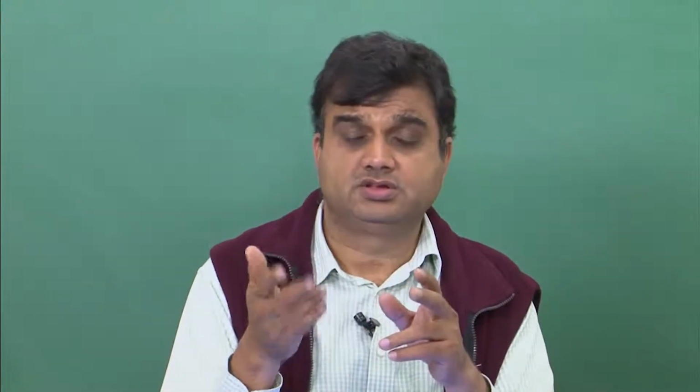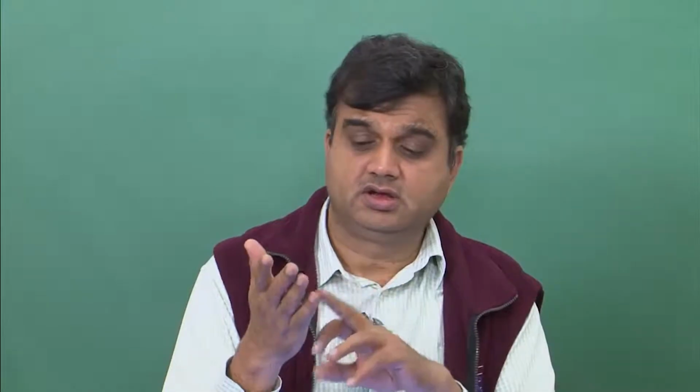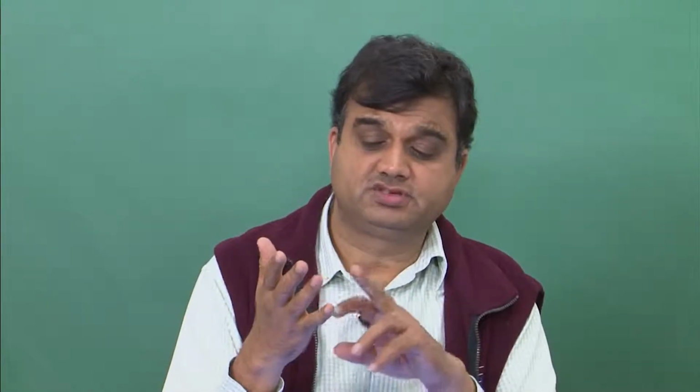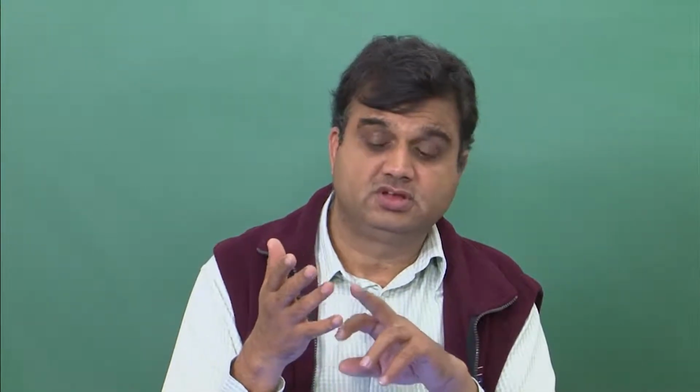One was resistance based microphones, and then the second category was capacitor based microphones. And in capacitor based microphones we had discussed several categories: DC biased microphones, RF microphones, electret microphones. So now what we will do is we will continue this discussion further.